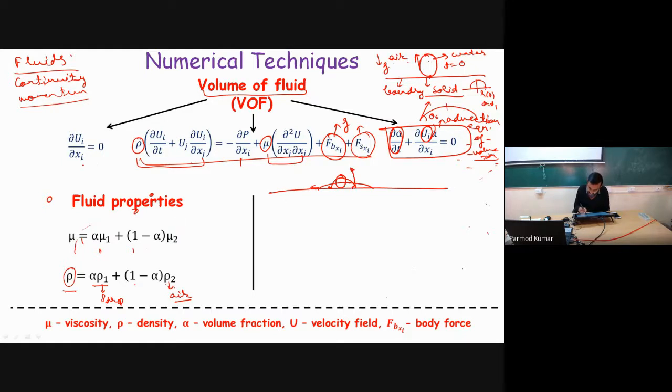Okay, so we have to assign some boundary condition which will be telling us that when this interface is touching the drop, for example, the interface may be like this, at the same time the drop may be like this, at the same time the drop may be like this. So depending upon the value of the dynamic contact angle, we have to supply a boundary condition at this solid surface which will be determining the shape of this contact angle.